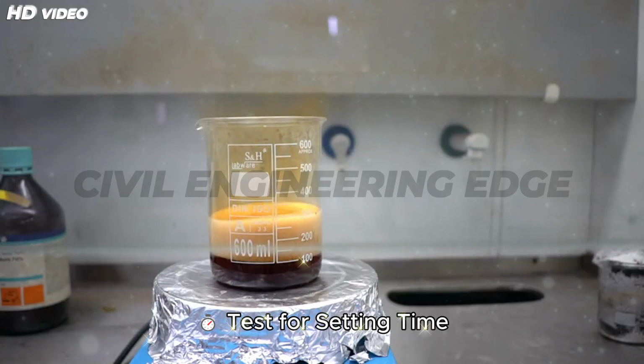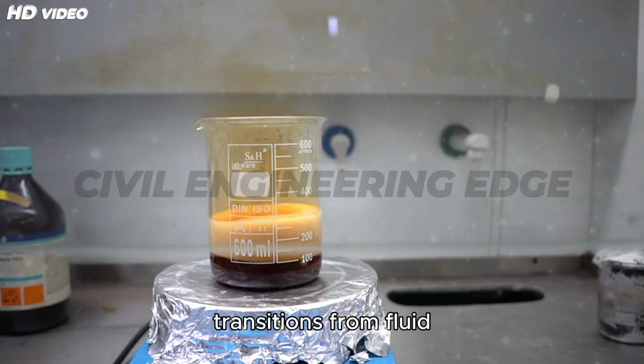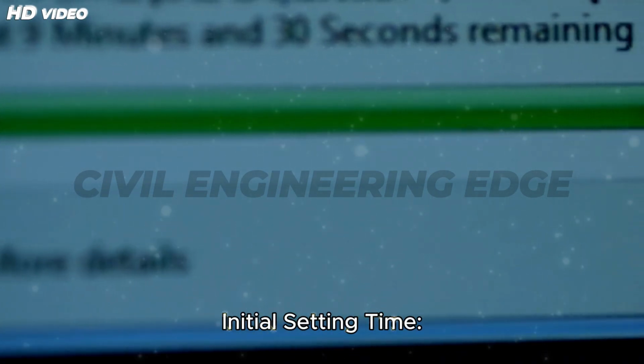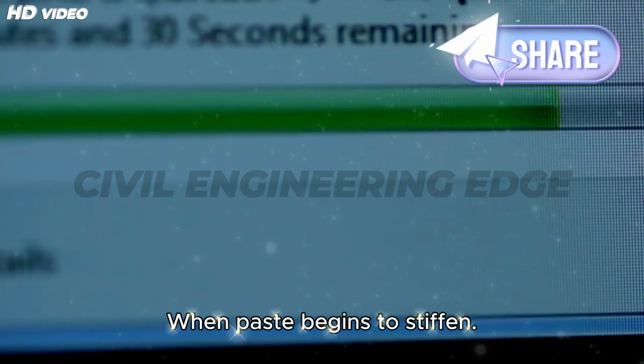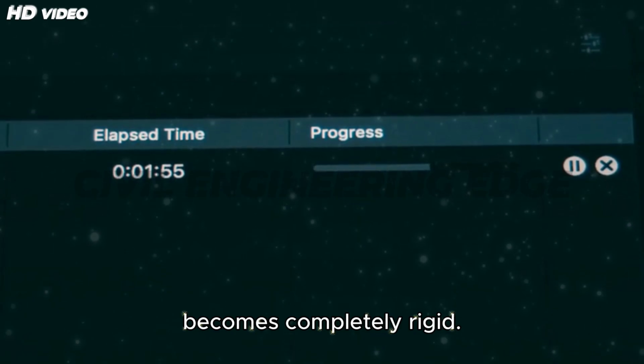Test for setting time of cement. Setting time defines how fast cement transitions from fluid paste to hard mass. We test for initial setting time, when paste begins to stiffen, and final setting time, when paste becomes completely rigid.